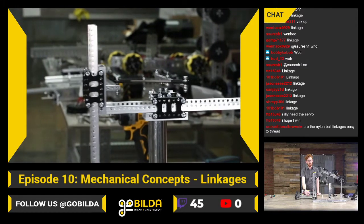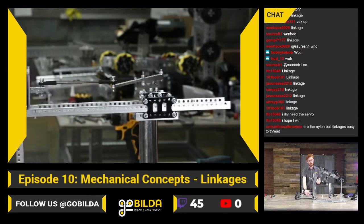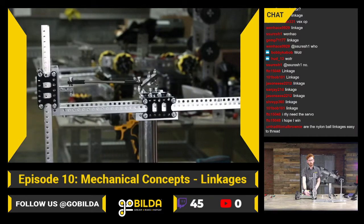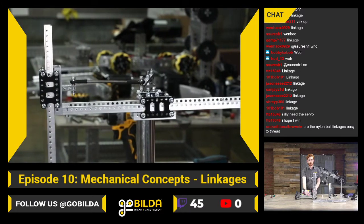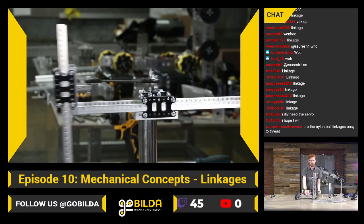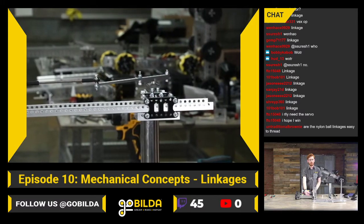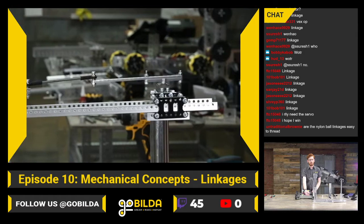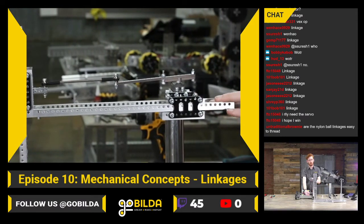This right here is the point where we have the most throw per degree of rotation of our servo. So this part of the linkage right here is where we hit a ton of rotation without moving the servo. We hit a ton of linear movement without moving the servo very far at all. Now, when you get out to this point right here, you can move the servo a lot more and not move the linkage, or not move this linearly very much at all.